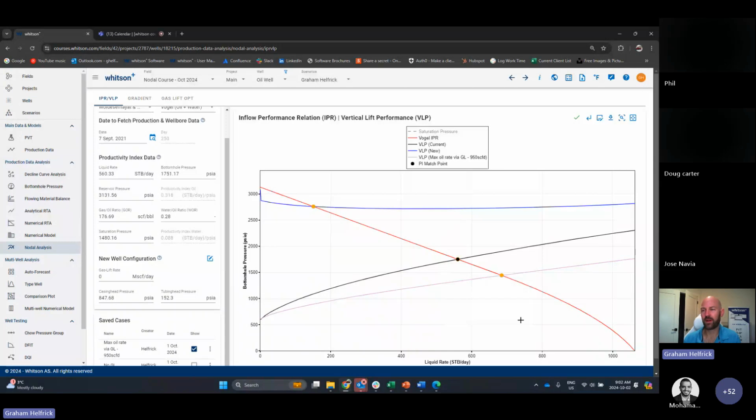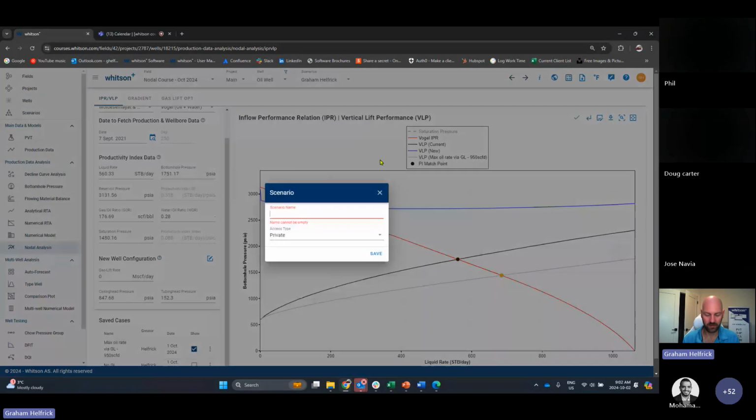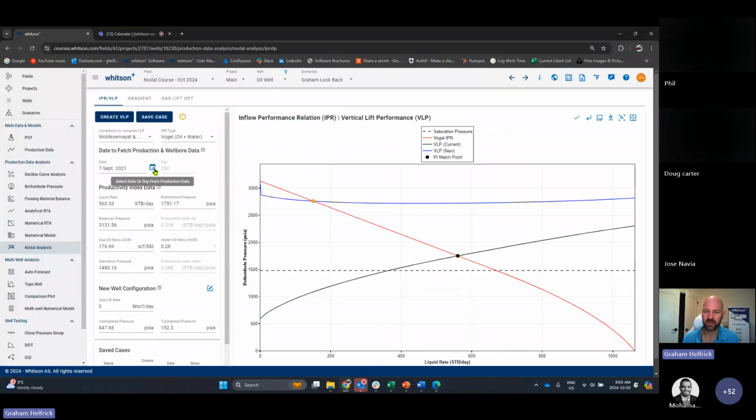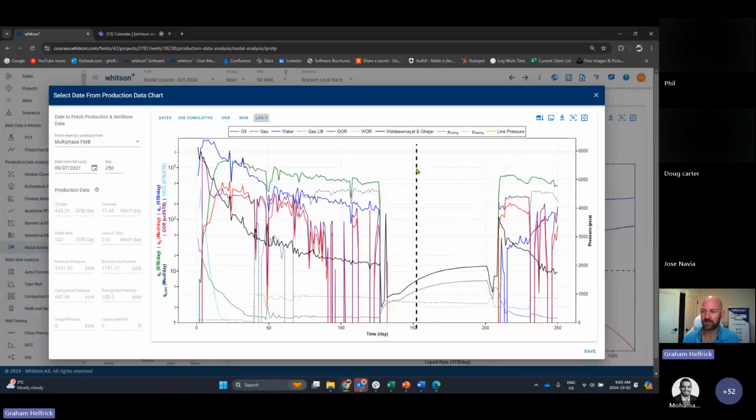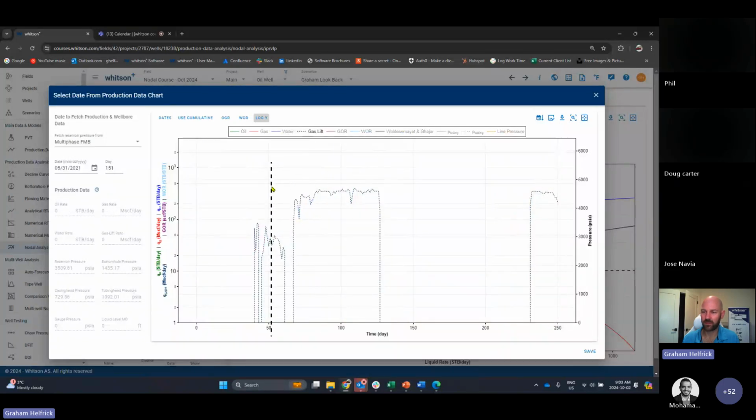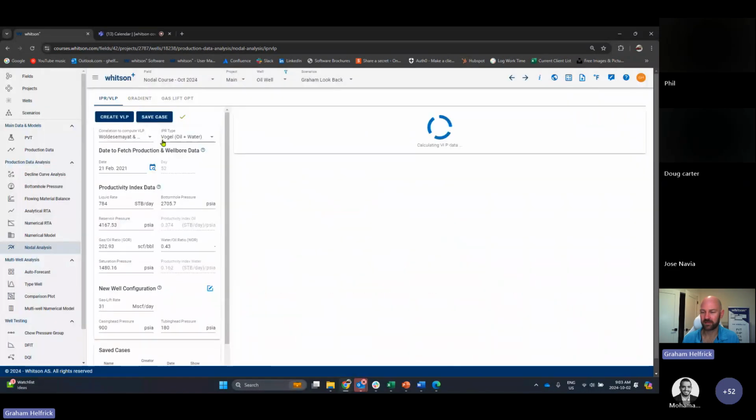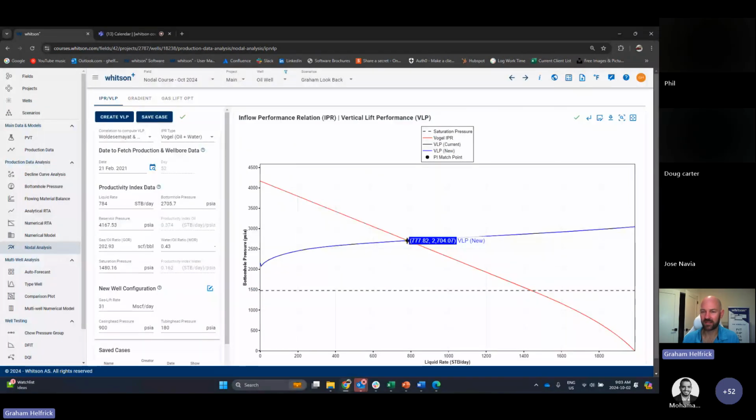All right. Now, the next thing I'm going to do, I want you guys to watch. You don't necessarily have to follow along. I'm going to call it a grand look back. I'm going to recreate from the well's history a little bit earlier, back to when the gas lift rate was a little bit lower. The gas lift rate was only around 30,000 a day or so. When I pick this vertical point, it's sampling the rate, the bottom hole flowing pressure, and even the average reservoir pressure at that time, which was higher, 4,100 pounds, according to the flow material balance. These are my conditions back then when I had a low gas lift rate.